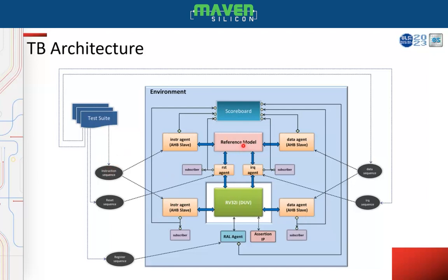Whatever stimulus we are driving to the design, the same stimulus is driven to the reference model also, so that the reference model will produce the expected output during the execution of load and store instructions, and that will be sent to the scoreboard. At the same time, the design's outputs will also be captured by the output monitors and sent to the scoreboard, and the scoreboard does the validation.